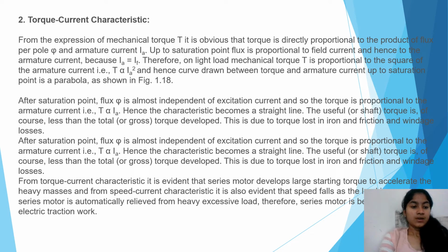From the torque current characteristic, it is evident that the series motor develops large starting torque to accelerate the heavy masses, and from the speed current characteristic, it is also evident that speed falls.